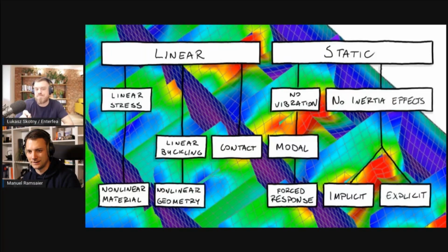This would be the perfect outcome. This would be called critical capacity in Eurocode. So like Euler buckling, the Euler's force is not the capacity due to buckling, it's the perfect ideal capacity of ideally elastic buckling of this perfect representation of an imperfect system.